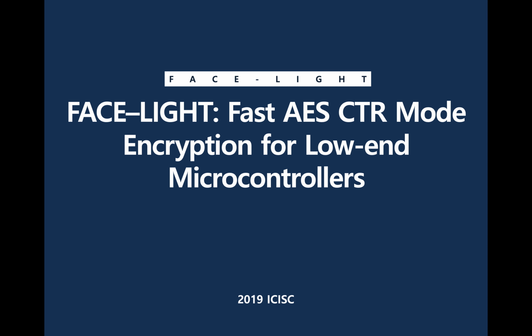Today I'm gonna give a presentation about FACE-LIGHT. FACE-LIGHT is an improved implementation of FACE, which is another AES optimized implementation that was introduced in CHES 2018. FACE uses lookup tables that are too large for low-end microcontrollers. So we have reduced the size of the lookup table so it can even be used in 8-bit microcontrollers. Also, we have removed the need to update the lookup table.